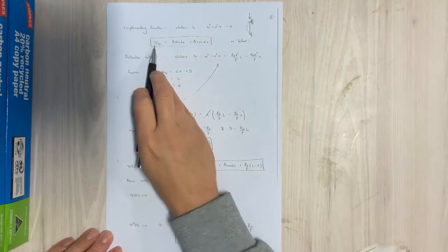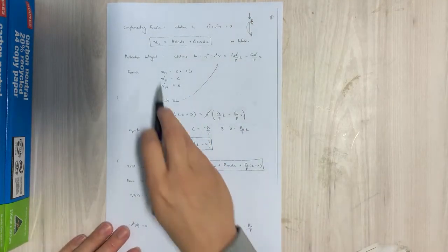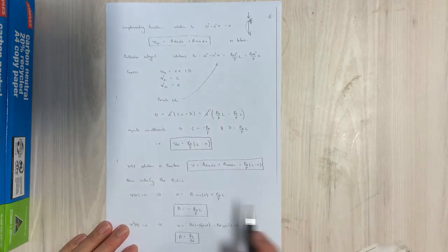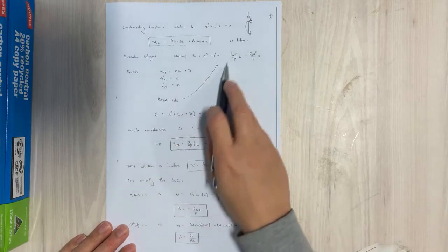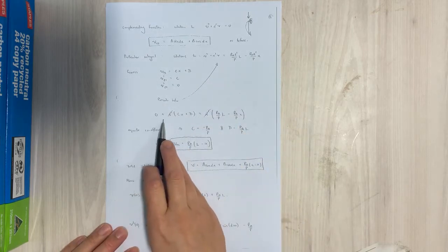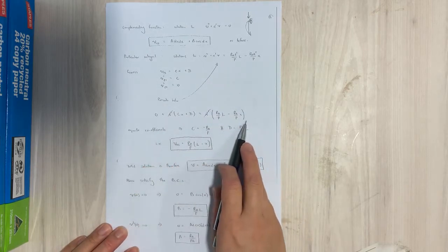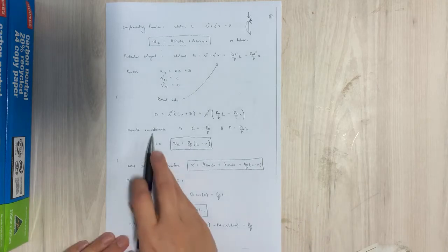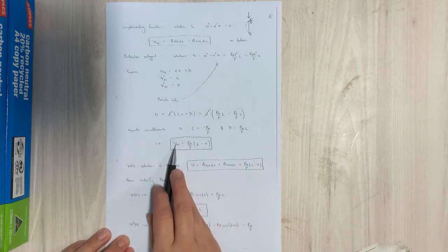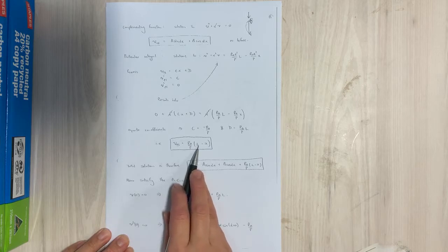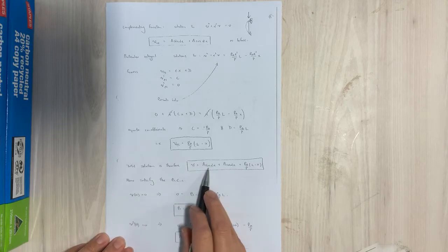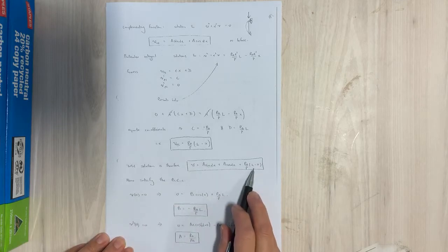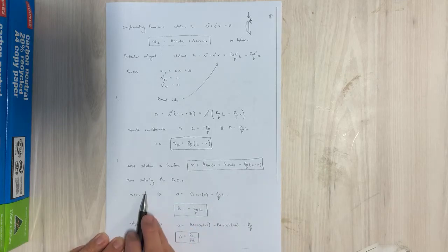So complementary function VCF. We can now guess some values, effectively just putting in the boundary conditions. So we set the boundary conditions, and then we re-express in this simpler form, equate the coefficients, and then we get VPI, the particular integral, which is RA over P times L minus X. The total solution is therefore the complementary function plus the particular integral, and now we put it through the